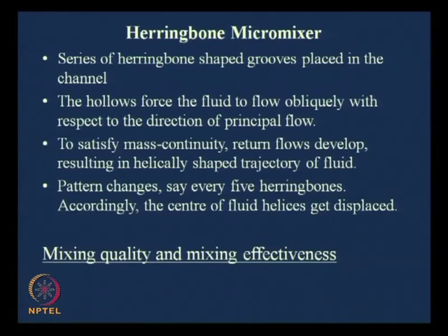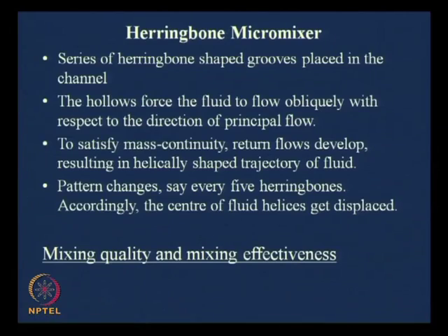So, there are various mixing strategies. We discussed various mixing strategies. On one hand, you have sequential segmentation, where you introduce a solute pulse, and then another one followed by a solvent, so that this pulse can now diffuse into the solvent slowly. That is one way. The other way is you can induce cross flow by putting grooves, putting hollows on the floor. So, that is one method.